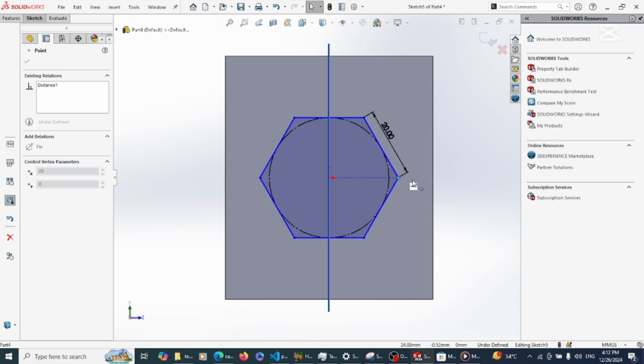So I can see that white line is showing. White means we can make this point and that origin vertical. See the blue dashed lines. You can make it horizontal, but then it's not horizontal, but that's a possible relation. You get it? If it was here, it will automatically just do it for us.